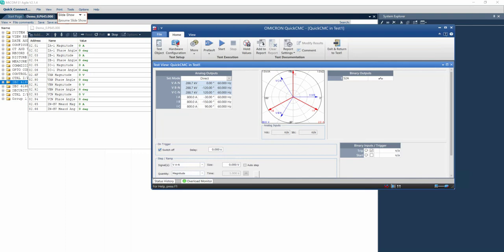Just simply by this output here, when I click it, I need to send a GOOSE message. So when I click it on and off, to resemble opening and closing the circuit breaker, I want that to be translated to a GOOSE message and sent out, or published, on the network. Then we will configure the MiCom to receive that GOOSE message. That's going to be the main discussion of this video.